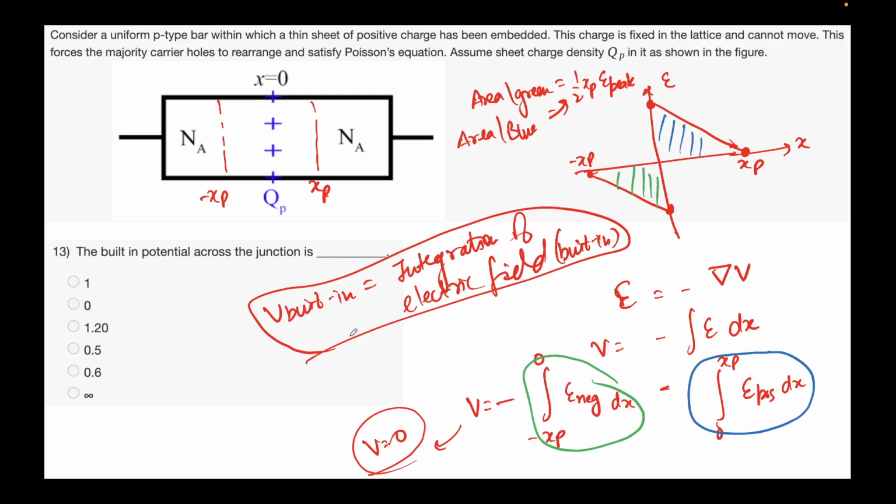And then when I drew the E_C, E_V, I told you that you see this bend, that it's a parabola. Again, that built-in potential was arising due to an electric field. If you integrate that, you get the built-in potential. Same principle, that's a principle of physics. The device may change, you can incorporate positive charge, negative charge, any number of charges. The Poisson's equation will still stand. It has to stand.